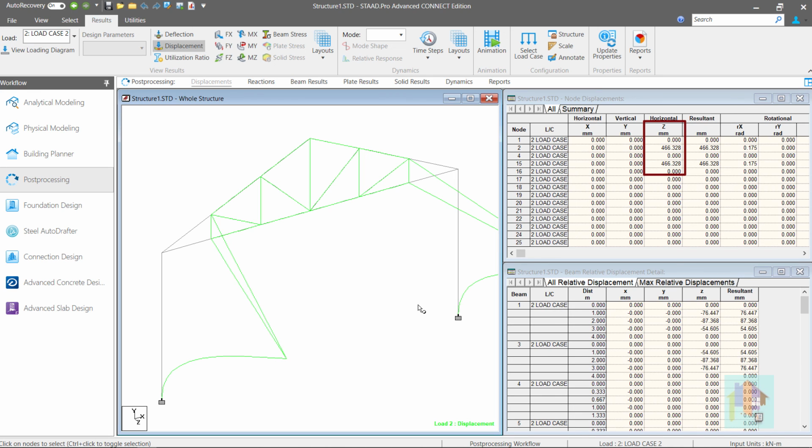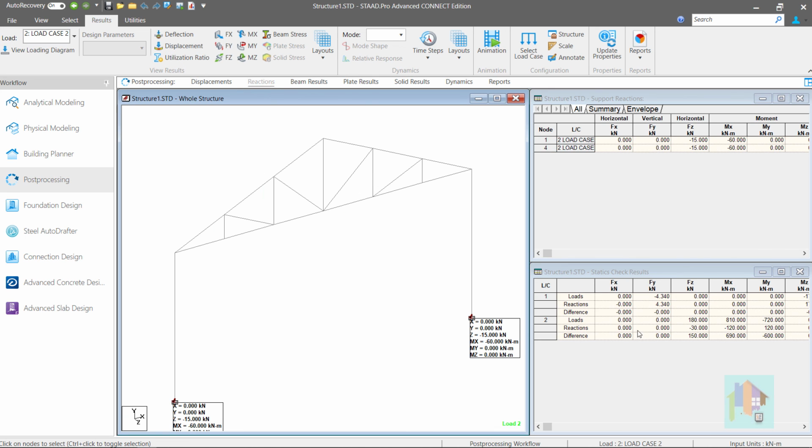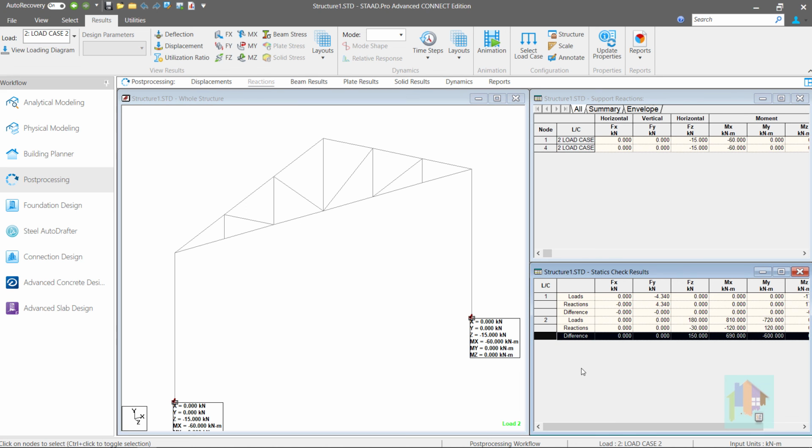See the deflection diagram for this load case. The deflected members are out of screen. As there is no stiffness in the Z direction, due to the applied nodal load in Z, the deflection is almost half a meter. This is not acceptable for any structure. For this load, the zero stiffness condition not only causes load mismatch, but also a large deflection value. This model is structurally unstable and must be rectified.